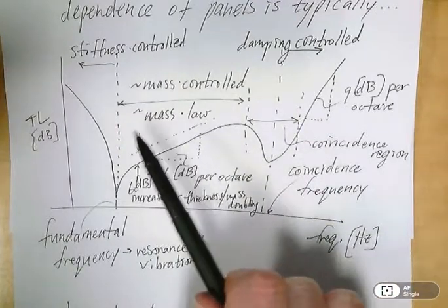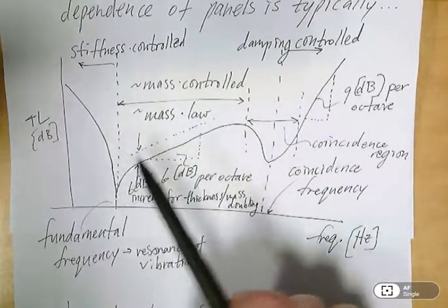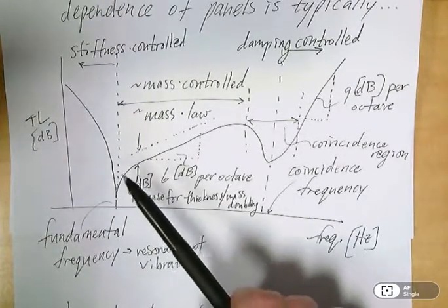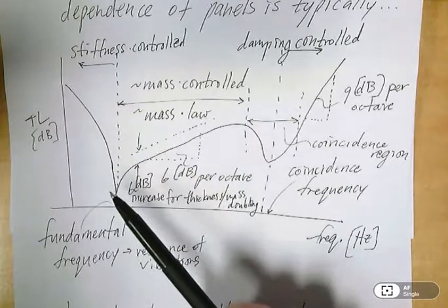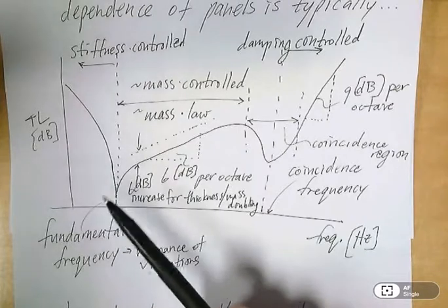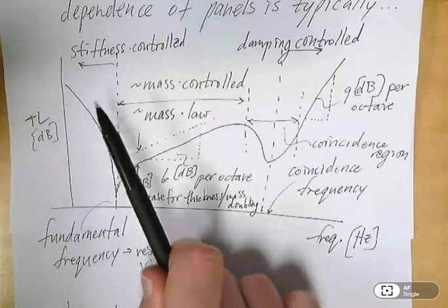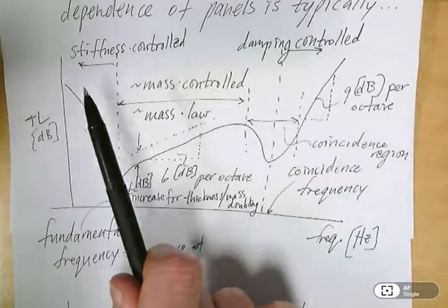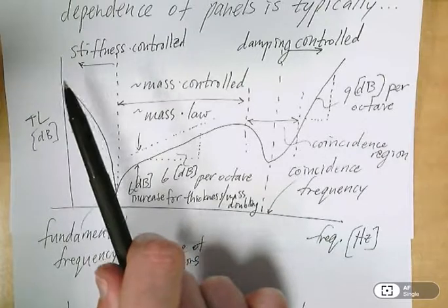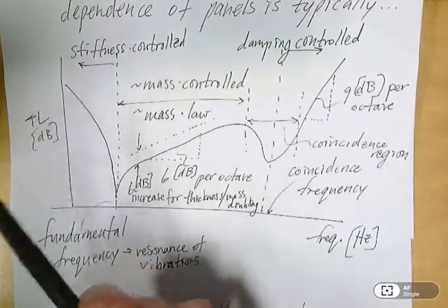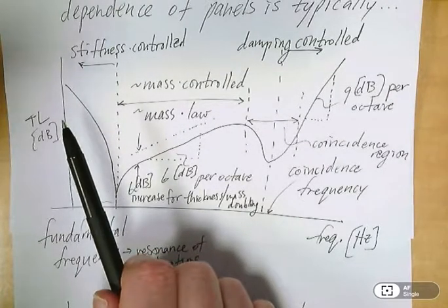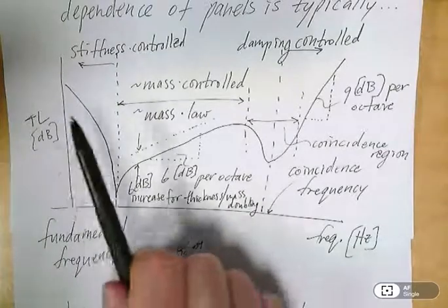Now, at the other side of this, we have structural vibrations and resonances that prevent this mass law trend from going on ad infinitum down to lower and lower frequencies. Because in fact, at some point, very much of the incident wave energy is propagated through, so the TL is very low when we have resonance. But below that frequency region, we're basically stiffness controlled, and in fact, transmission loss grows, but not ultimately infinitely. It grows to a finite value, because we of course know the wavelengths are so long in this region that base frequencies, long wavelengths, are not ultimately prevented from passing.